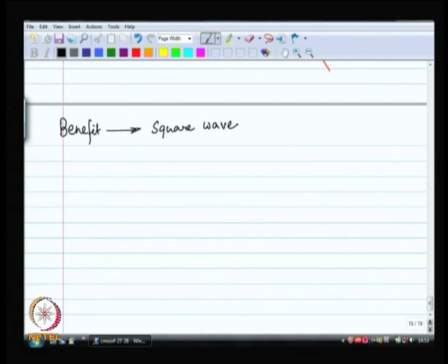All right. Why do I like square waves? I think we talked about this before. We like square waves because the noise is only the phase noise. The amplitude noise is irrelevant because it is a square wave, right. Wherever there is any noise in the amplitude, it is cleaned out because you have got plus and minus VDD or the power and ground as your voltages. So, there is no noise as far as the amplitude is concerned,